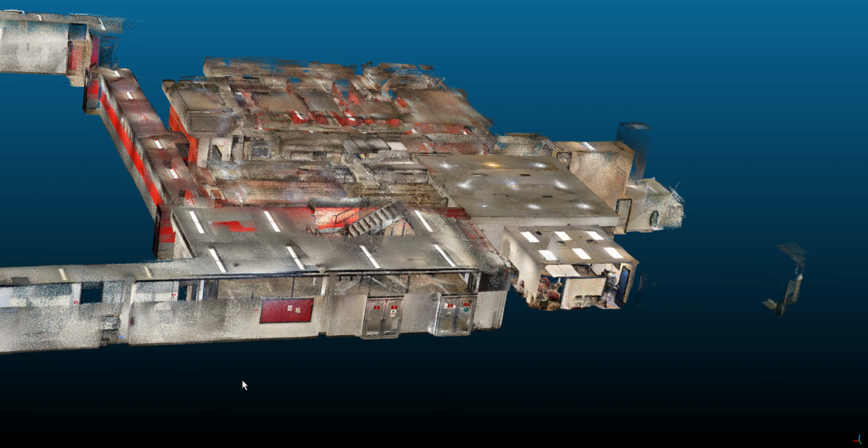And then the final issue is that you have to look out for situations where you take a scan one day, pause it, and then take another scan another day, and you might notice that some objects are shifted around. This is very common for doors, for example. You might have a scan of a door being open, and the next day the door could be partially closed or even shut, and it would turn out different in your final result.